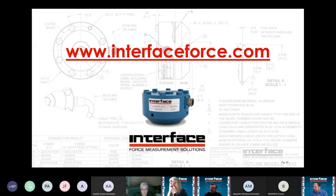All right, great. There's another question about load cell applications at variable altitudes, and I think that's a great question. We certainly have the ability to handle different pressure scenarios. A lot of our product is sent out vented if necessary to be able to tolerate pressure change without causing any zero shift. So again, if you do have applications where you will have either high pressure requirements or pressure change throughout the test, we certainly have solutions that can accommodate that.